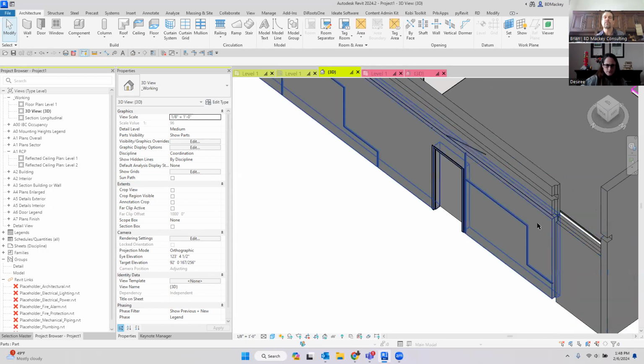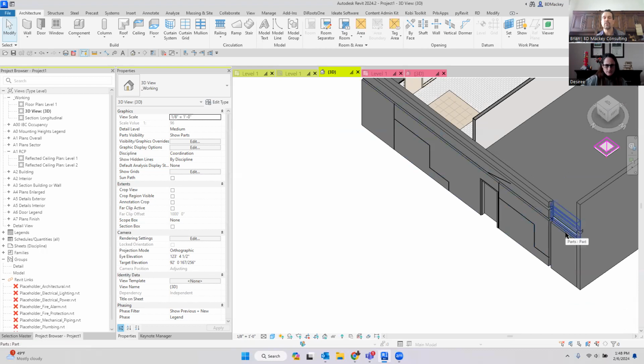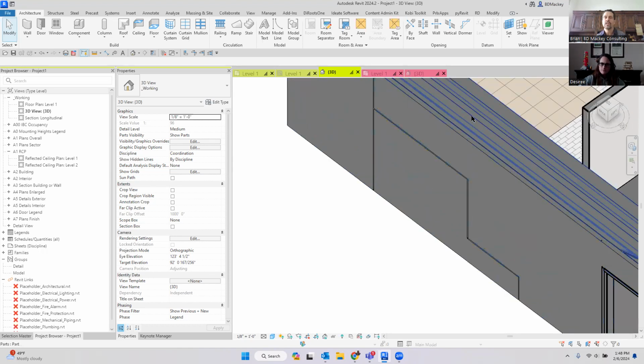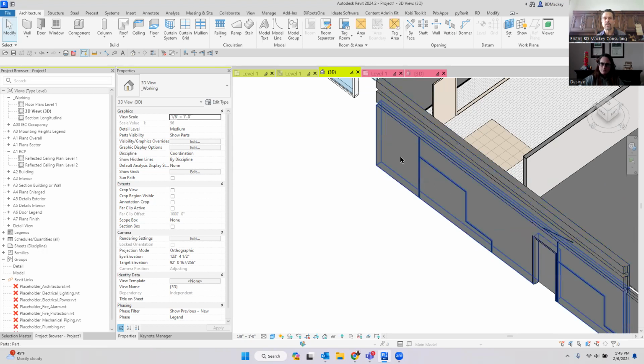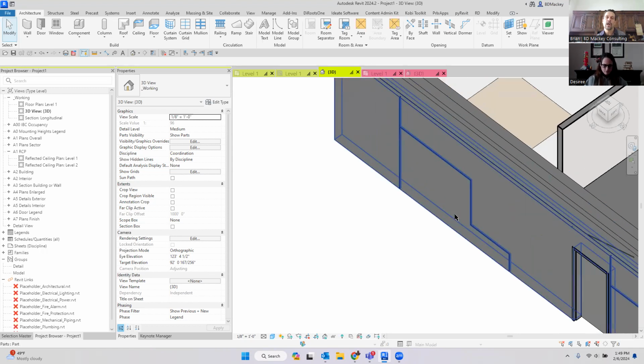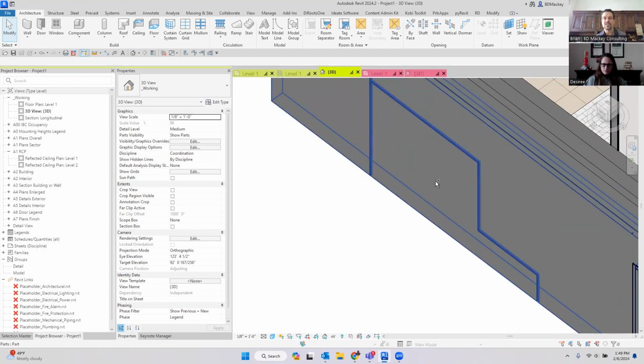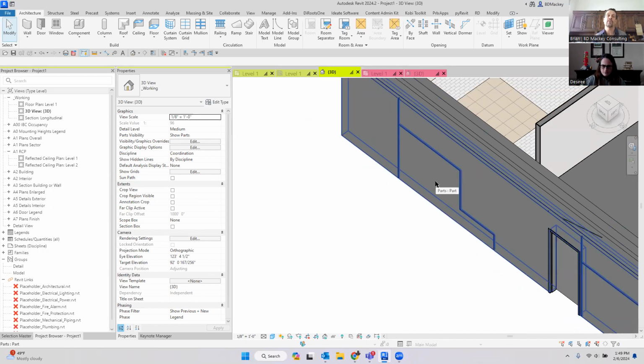But if I didn't want that reveal to go all the way across, then it's the add, remove, click, click, click to reveal that mullion, and having to remove the curtain wall grid to get that to do what I wanted in different patterns. As in curtain wall, this would have been a grid line going all the way across. I would have had to remove, remove, remove, and you're spending so long doing that. And then if that was the case, this could not be a custom panel right here because custom panels have to be rectangular.